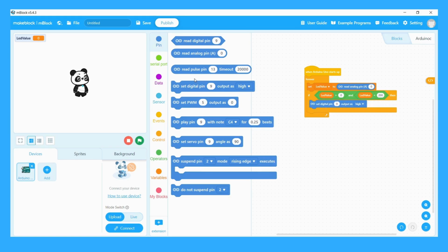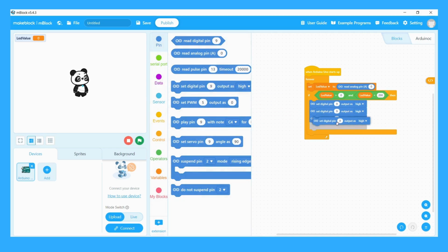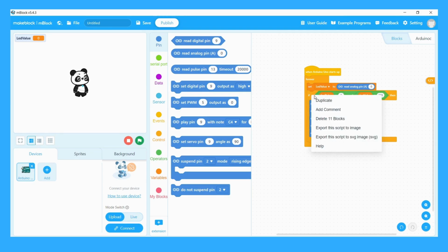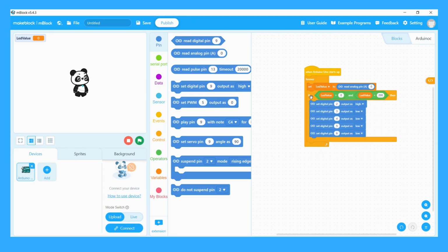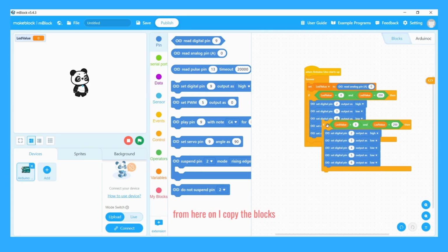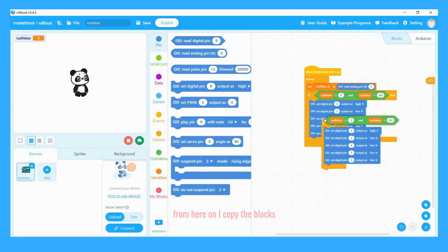To keep it sequential, I will activate the digital 2 pin to which my first LED is connected and deactivate the other digital pins. Now, I will divide it into 200 unit parts sequentially and activate the other digital pins in order.